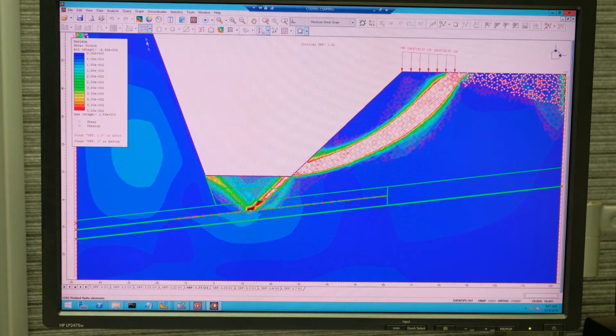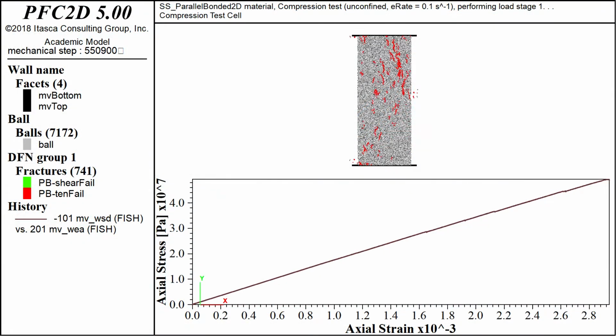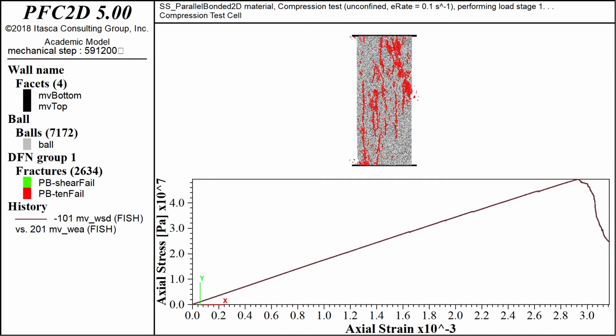Geomechanical data can be acquired from laboratory testing of samples obtained from exploration drilling. Strength data is also estimated through the back analysis of failed slope geometries using geotechnical modelling software and either limit equilibrium, finite element, or synthetic rock mass modelling techniques.